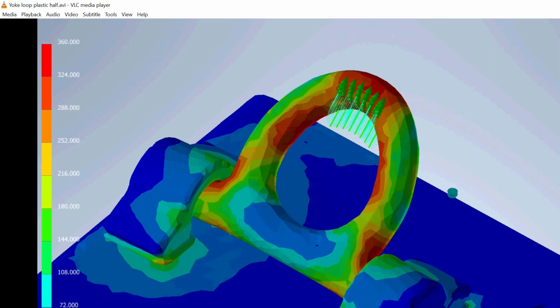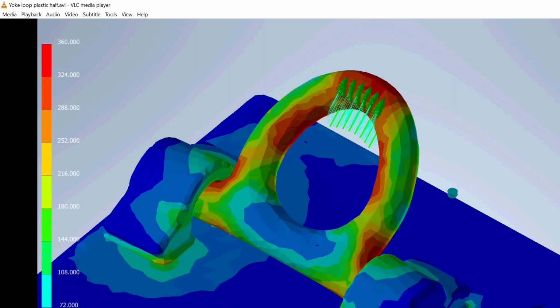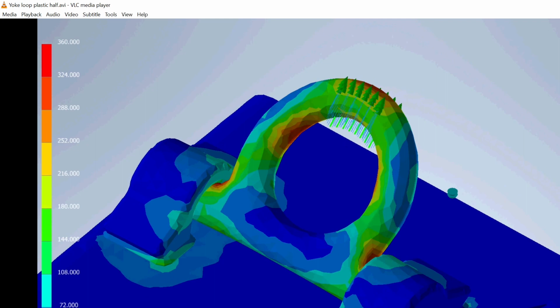So frequency stress limits of cyclic stress limits should be checked on that as well. But if you did a simple linear elastic simulation and you stay below 260 in this case for S355, then you know that you are within the endurance limits of the metal, and it will technically never fail as long as the loads don't exceed the design limits.